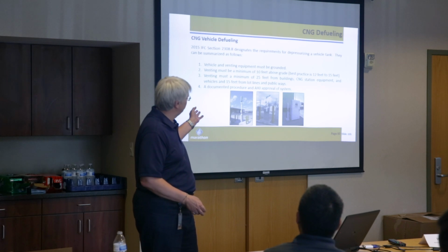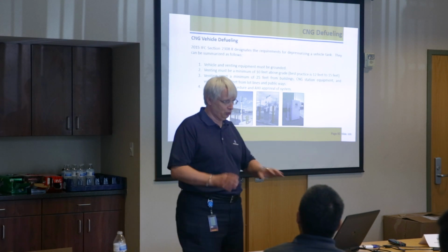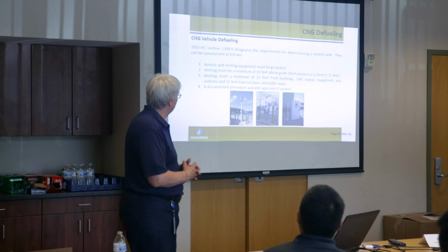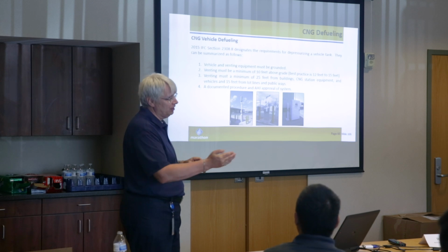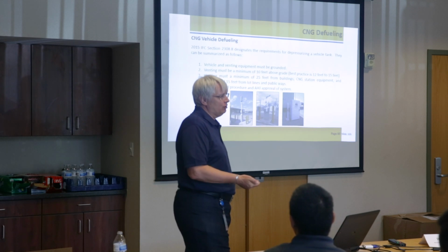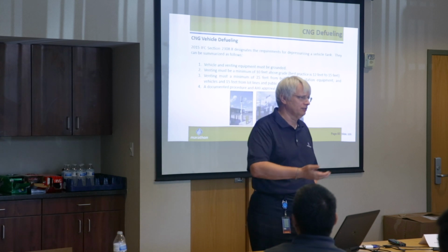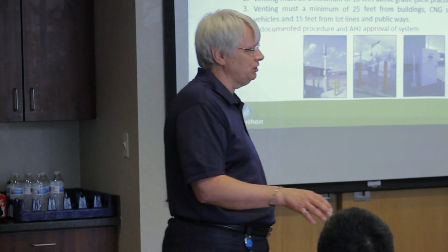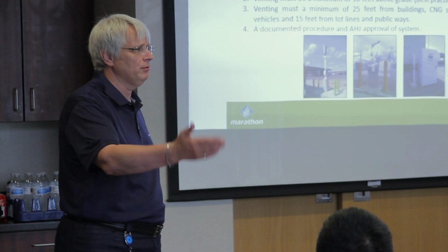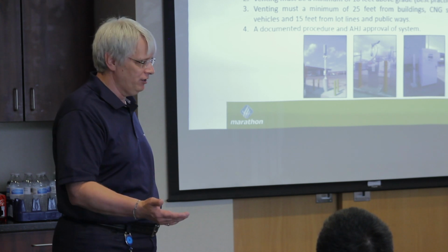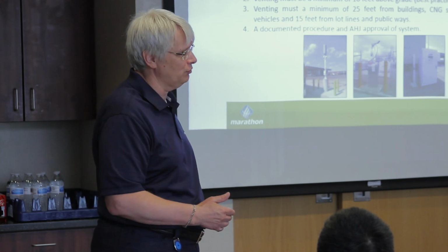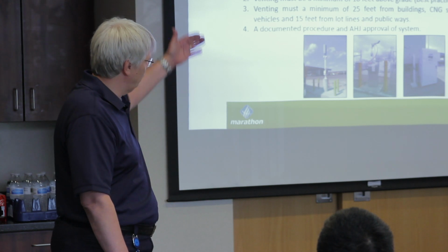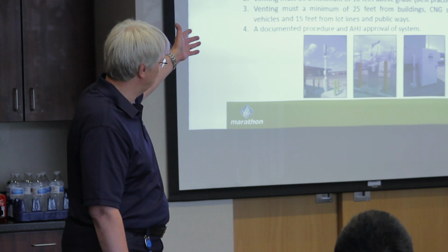2 different requirements, one for CNG, one for hydrogen. It shows up in 2 different code sections. The International Fire Code 2308 has requirements in there, and they actually don't call it defueling. I think it's cylinder depressurization or something like that. They don't specifically call it defueling. And so there are some people that say, well, maybe you're not really required to have defueling. So that's the discussion you can have as an owner and with your AHJ. If you're going to defuel though, there are a number of requirements and you can see them listed here.